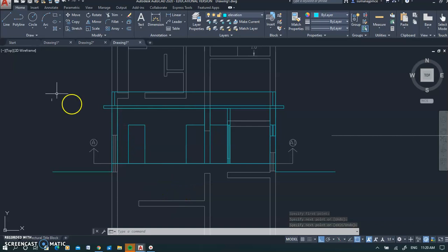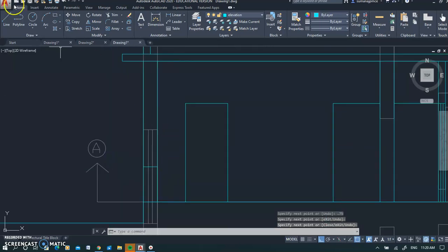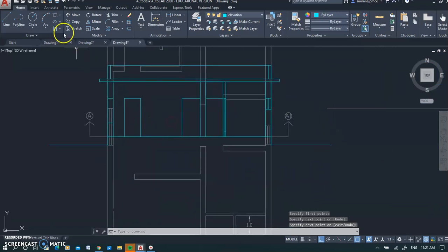And there is one more window which is cut here, so we can start from the ground, and we know the window sill height is 0.75. We come on to here, and we know the window will stop at the door height. You don't need to keep measuring and knowing the measurements, because you've already done it in plan.